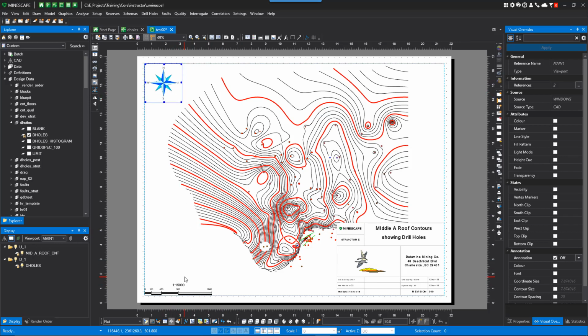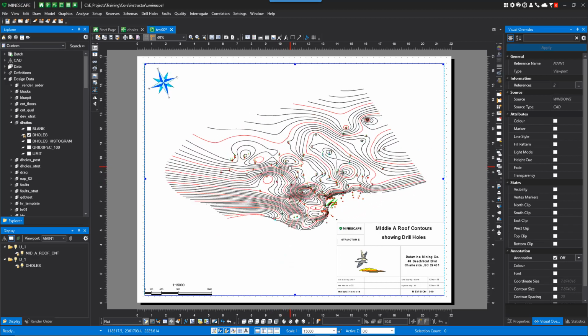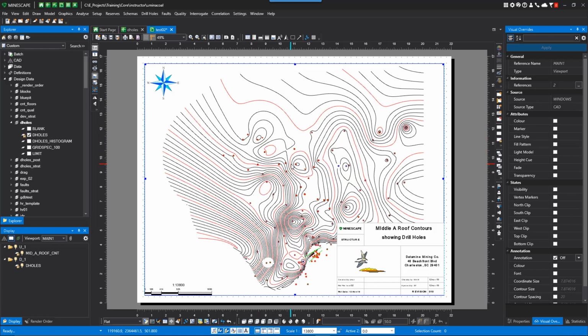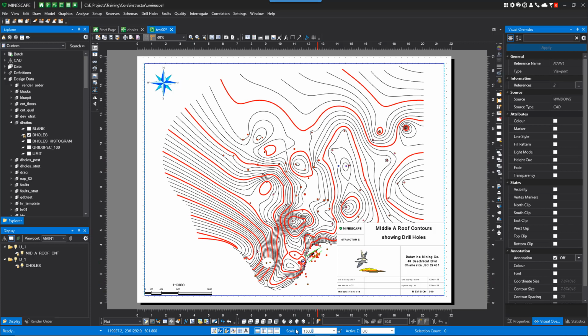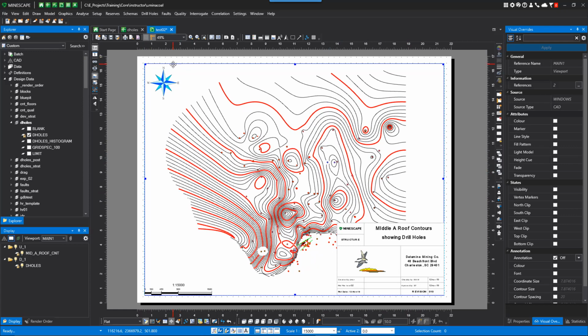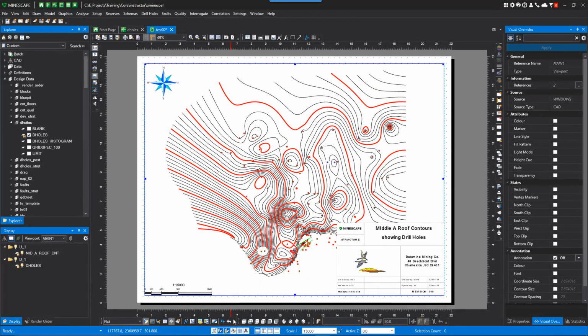And this scale bar and this north arrow are linked to this data. So if I rotate the data, you can see the north arrow changing. I didn't lock my scale because I didn't need to. I can pan it around. I can save that, or I can print it. Print preview, and I noticed I didn't have my annotations on, which is a great thing to print preview. I can turn my annotations on and I can go ahead and print this. So it's just that easy to do, plot designers.